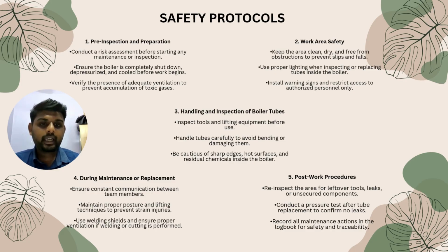Today I'm going to talk about the safety protocols for boiler tube work. Firstly, we need pre-inspection and preparation. We need to conduct a risk assessment before starting work, and we need to ensure that the boiler is completely shut down, cooled and depressurized.